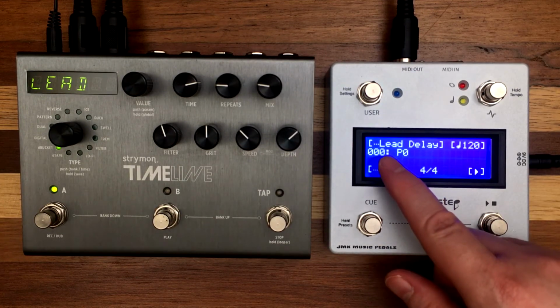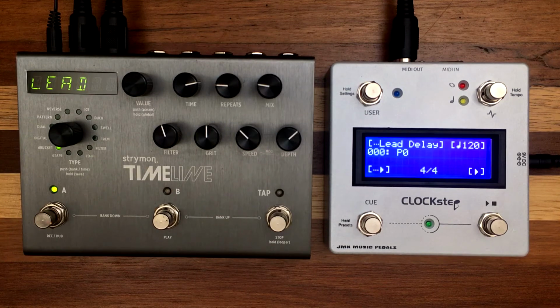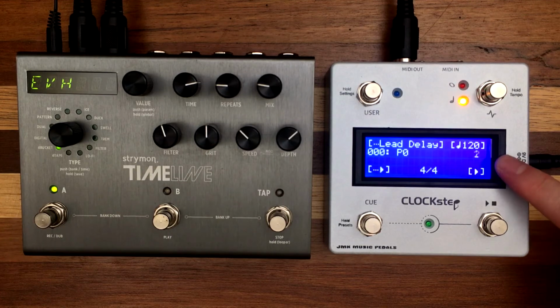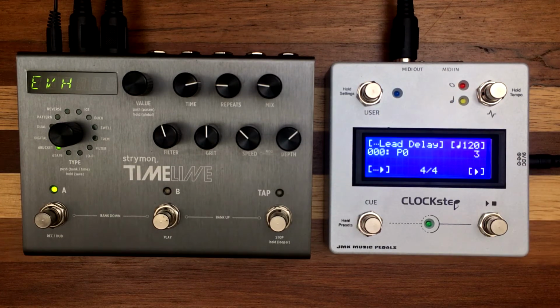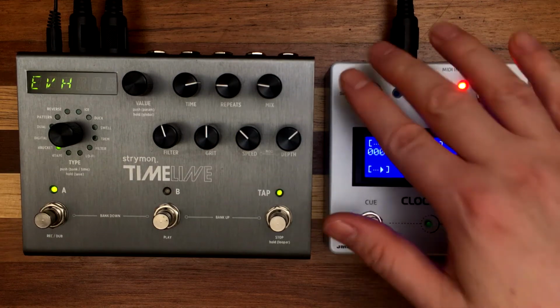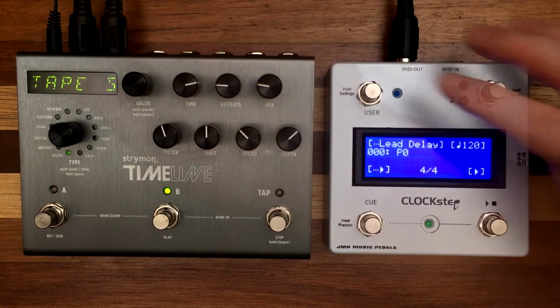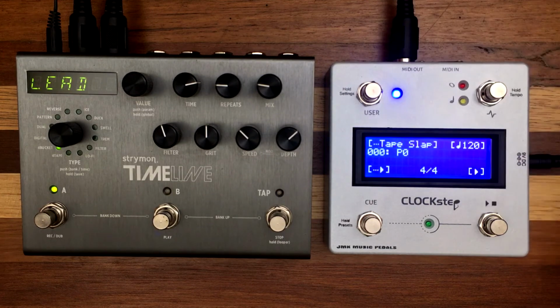As before, we can see the name of the MIDI command on screen, but now it's prefixed with a dotted icon. That icon indicates that the command will wait to execute on the next bar. You can see that the clock is counting off in 4/4. Now when I press the user switch, the LED will flash, indicating its pending execution, and will go steady once the command executes on the first beat. Again, the name of the command changes on screen to indicate the next command. Additionally, when the clock is stopped, the queued toggle command works just like the toggle command without queuing.